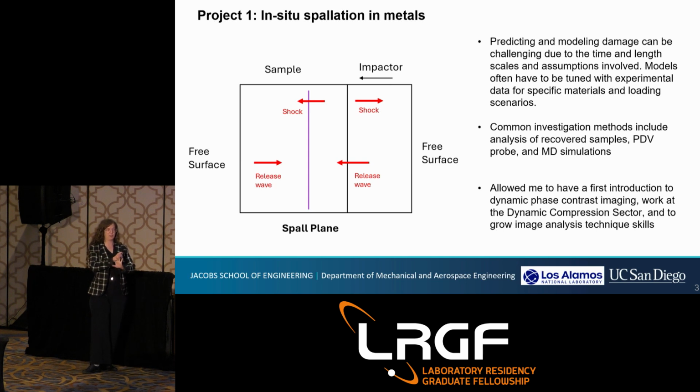And then where these release waves cross, you get a plane where you have a region of tension, which creates voids that nucleate and then grow and coalesce together, and you end up with failure at this point as things rip apart.